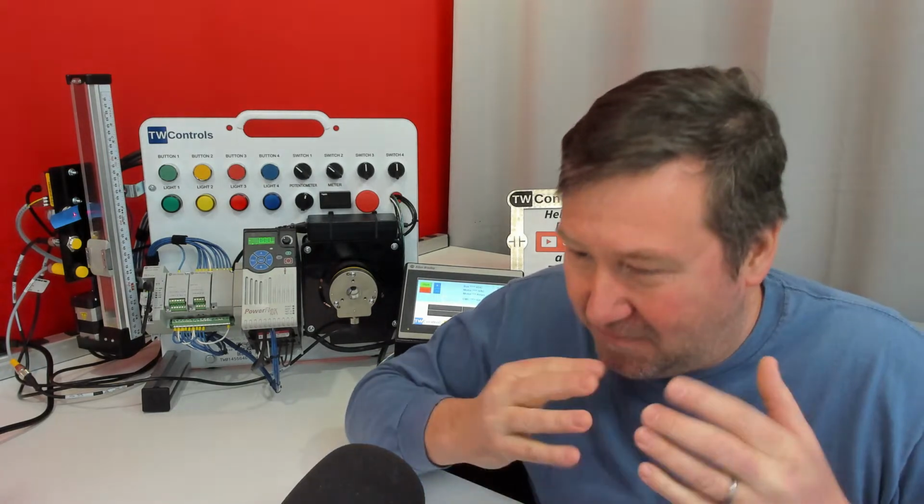Really, the last few have been getting our data, being the process and control variable, ready for the PID. The next thing we really need to talk about is the update rate. How often do you want this PID to update? I ask this question, and usually people say as fast as possible. And that's usually not the case.